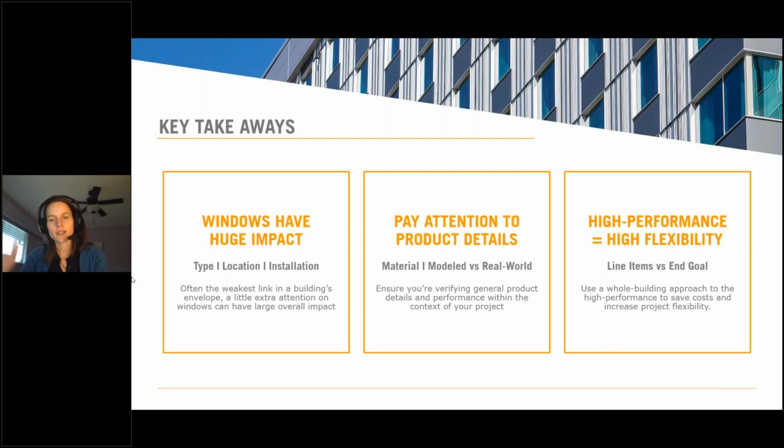So it's really designed as a slab to slab kind of a window system. And if you have larger heights and spans, say continuous, like a foyer or something like that, then you would need to put in structure at approximately every story or so to support the weight of the window system. Hopefully that makes sense.